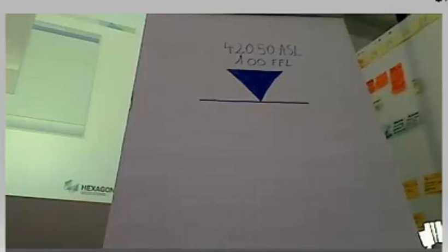On a building site, most of the time, they'll be working with the finished floor level height. So that means that somewhere there'll be a 0,0 height, and that would have been done by the surveyor, and that will be in relation to the ASL, so it's still to the sea level. And then any height thereof is going to be a derivation, if you will, from the 0,0 height. So you'll have your 1 metre finished floor level height.